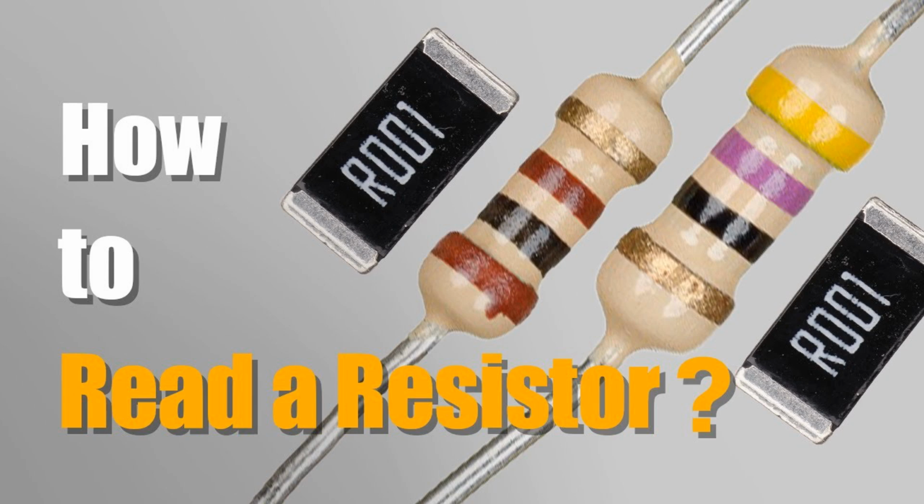Key parameters in filter design. Cutoff frequency, fc. The frequency at which the filter begins to attenuate the signal. In low-pass and high-pass filters, this is the frequency where the output power drops to half its maximum value, the -3 dB point. Filter order. The order of a filter determines the steepness of the roll-off beyond the cutoff frequency. Higher-order filters have steeper roll-offs and greater attenuation of unwanted frequencies.